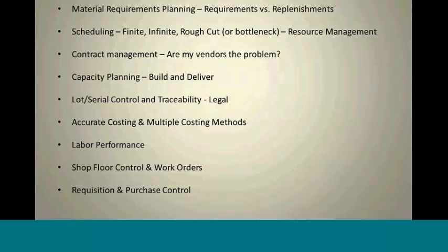Engineering change management is another great benefit. The ability to see how something was built is crucial for a lot of reasons. You always want to see how you evolved to what your product structure was. You want to see what those changes were, when you made them, and why you made them. You want to make sure that you have a formalized approval process so that once you make that engineering change, they're not building it the old way, and if the materials change, they're not using old materials.